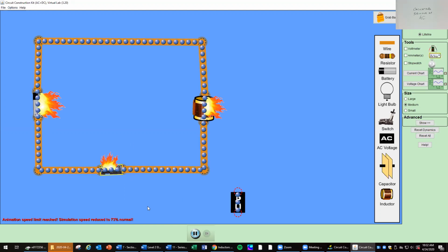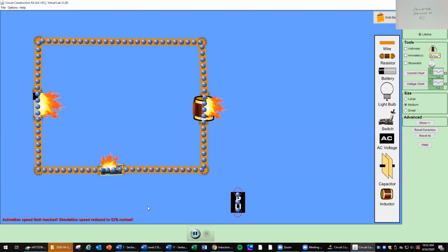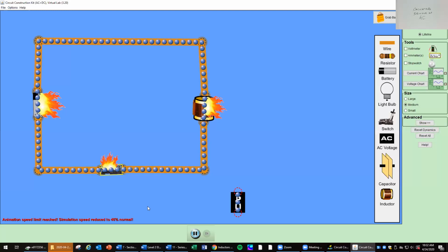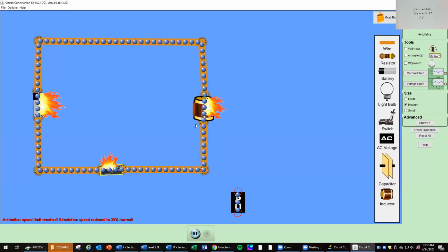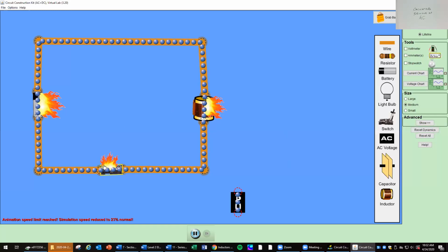And the reason for that is because the counter EMF gets less and less and less. So essentially what's going to happen here is the current is going to continue to increase in value unless I had a resistor. Because really, what's the resistance of this inductor? Well, it's just the resistance of the wire. So it could be like 0.01 ohms, which means there's a lot of current that could potentially flow. Whew, let's put out that fire, shall we?